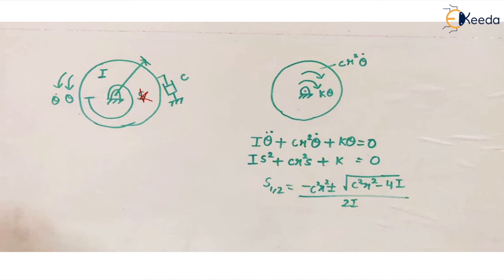Now till now what we calculated was for the linear displacement system, the linear displacement, linear velocity, linear acceleration. Now assume there is a system having rotational motion, torsional motion, connected to a torsional spring and a dashpot. What will be the equation? So the moment of inertia of the system, let's say, is I, and the angular displacement is in this direction, which is theta. The velocity and acceleration have the same direction. The spring force and the damping force will act in the opposite direction.